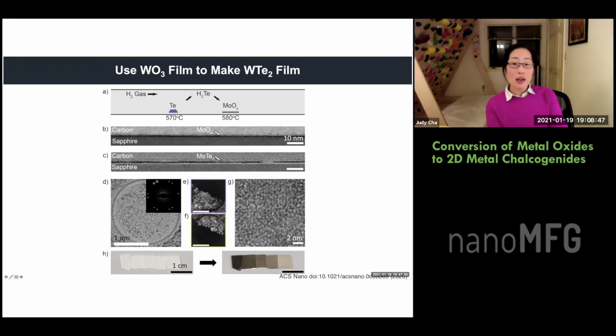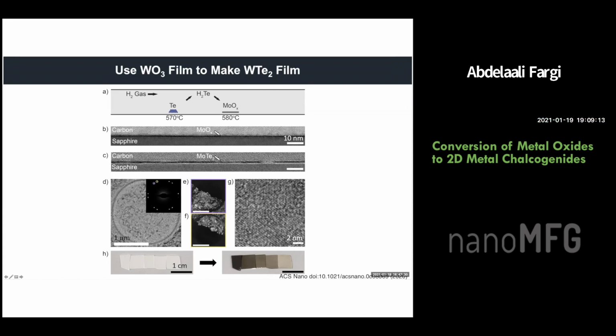For some of the films, we've also done TLM patterns, where you do a four-point versus two-probe measurement, to get a gauge of what your contact resistance might be. For now, we do a dry etch before we put down the metal contact. Okay, thank you.